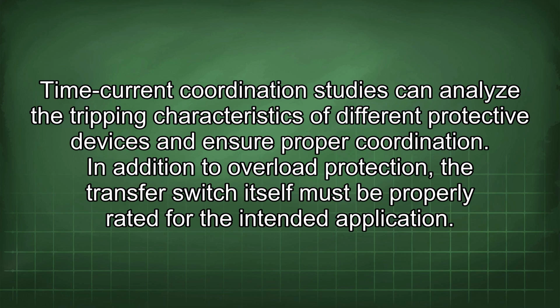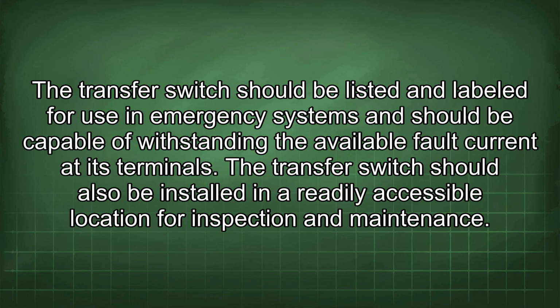In addition to overload protection, the transfer switch itself must be properly rated for the intended application. The transfer switch should be listed and labeled for use in emergency systems and should be capable of withstanding the available fault current at its terminals. The transfer switch should also be installed in a readily accessible location for inspection and maintenance.